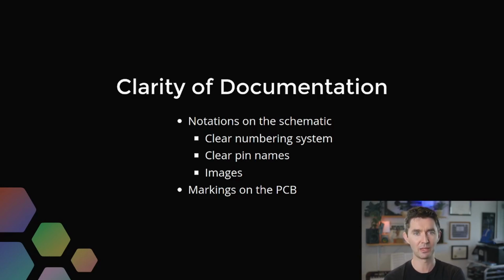RX and TX are well labeled. I take on the RX from TX2 sort of things, that you're verbose in your labeling of things, and hopefully very accurate as well, right? Make sure you go, if you are the firmware engineer, you're not only checking that the label is very verbose, but that it is correct. And then finally, marking stuff on the PCB as well.